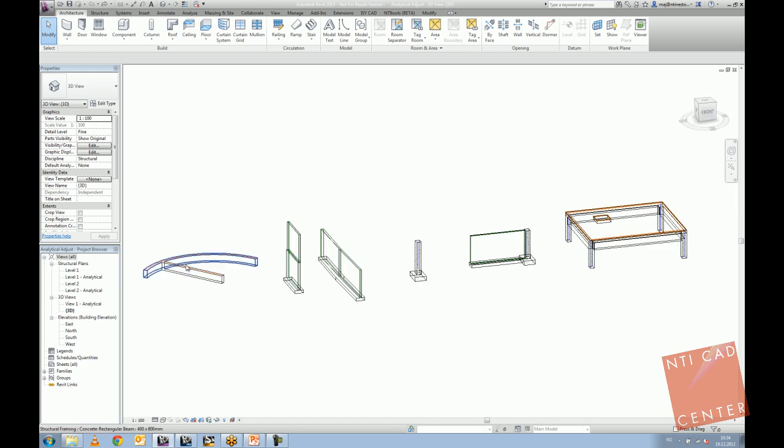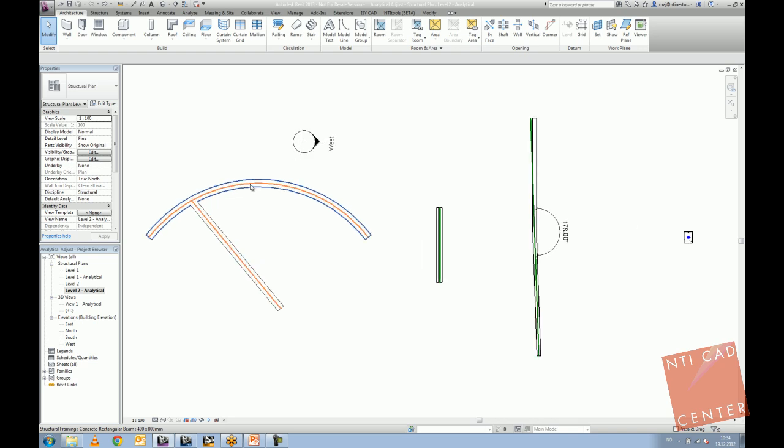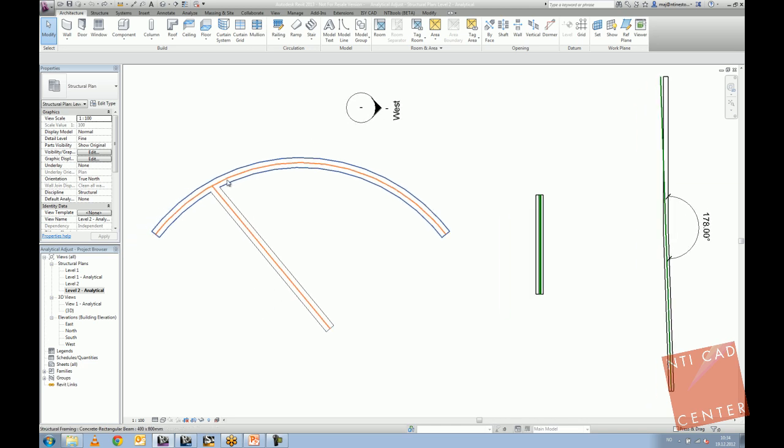What I have here is actually curved elements. If you have curved elements, jumping back to this level, what will happen when you send it to Robot? The good thing is that it sends the element to Robot. The bad thing is how it sends it, because if you don't specify anything else, your element will still be broken down into straight elements. So basically, node, and a straight line in between. But if you don't specify anything, you don't have control over how detailed it will be, so how long the lines will be.